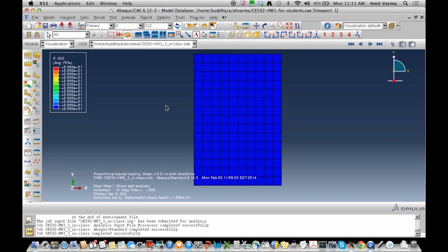This is what it's calling the von Mises stress. So it's trying to tell you that the von Mises stress is 50. That's what it's trying to tell you. It's the square root of 3 multiplied by J2. It's trying to tell you that, hey, I solved this J2 problem and the von Mises stress was always equal to 50. In fact, if I'm sitting on the yield surface, that had always better be equal to 50, right? Because my yield surface is defined by the fact that J2 is equal to sigma y squared divided by 3. So it's telling me that the von Mises stress is equal to 50 Ksi.